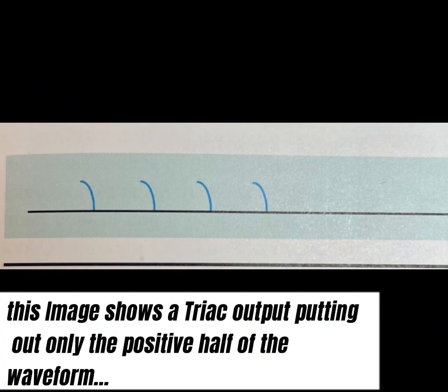For example, the synchronous speed of the rotating magnetic field in a two-pole motor is 3600 RPM when connected to a 60 Hz line. If this motor is changed to a four-pole motor, the synchronous speed will change to 1800 RPM.